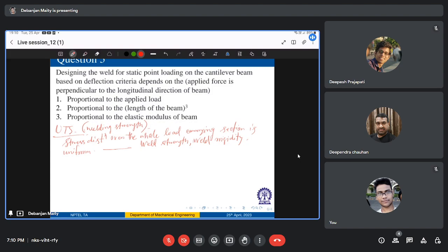So basically, you normally design it for the calculated loading, and for that you may have some design formula for strength, and deflection can also come into the picture. When you design using deflection, in many cases the deflection also should not be more than certain values, right?